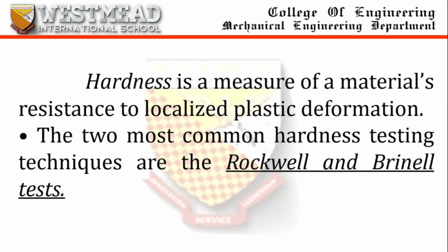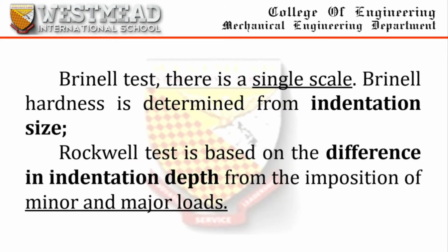So, yun nga, hardness is measured by a material's resistance to localized plastic deformation. So, there are two most common hardness testing techniques, Rockwell and Brinell tests. For the Brinell test, there is a single scale. Brinell hardness is determined from indentation size. However, the Rockwell test is based on the difference in indentation depth from the imposition of minor and major loads.